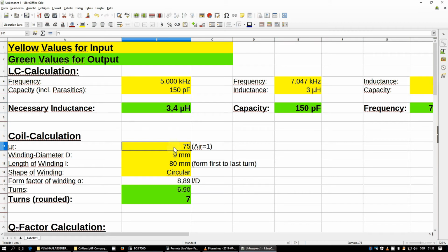even if we have the full data sheet and take into account the aspect ratio of our Ferrite-Rod, then it's more of fiddling around with the value to get the effective μr.